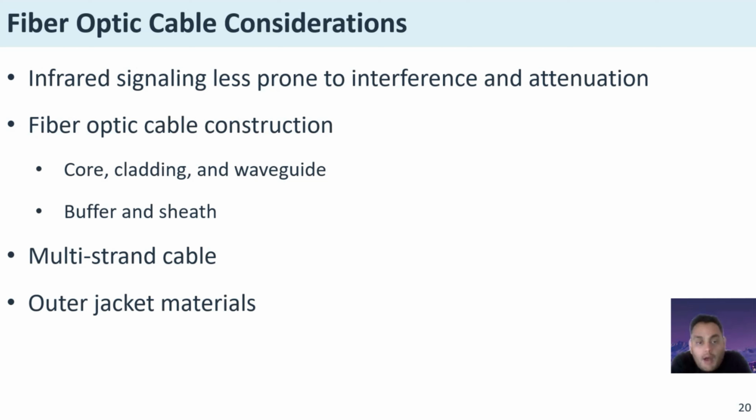A single optic fiber is constructed from 3 elements. The core provides the transmission path for light signals, otherwise known as the waveguide. The cladding reflects signals back into the waveguide as efficiently as possible, so that the light signal travels along the waveguide by multiple internal reflections. The core and the cladding can be made from glass or plastic.